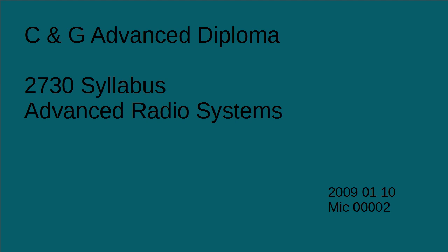Then what is the power that will actually be collected by this area? How do we find the electrical effective area? Assume that this also has a gain of 100, same type of antenna. Earlier, your table has the relationship between effective aperture and gain. If you know the gain, you can find the effective aperture.